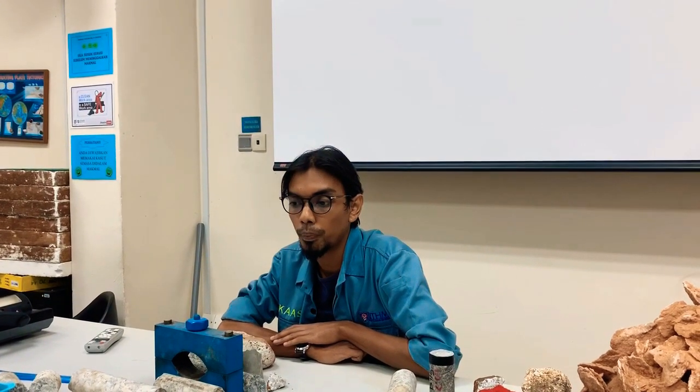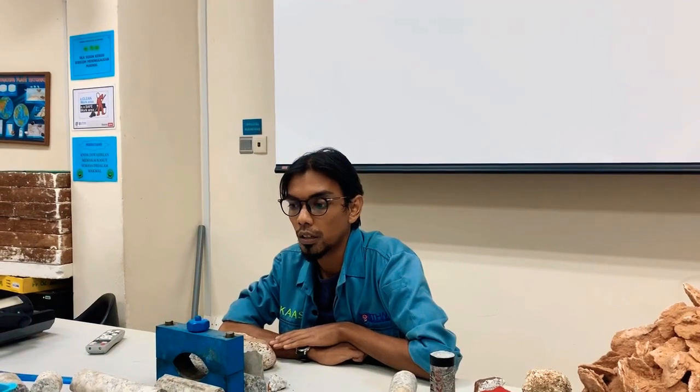In terms of treatment depth, this technique is limited to 2.5 meters or 8 feet as uniform mixing, and beyond that limit it will not be effective anymore. In some cases, bucket mixing may extend to 4.5 to 6.2 meters.